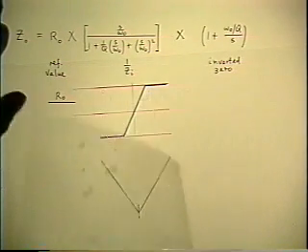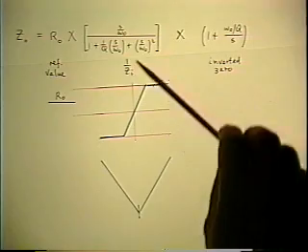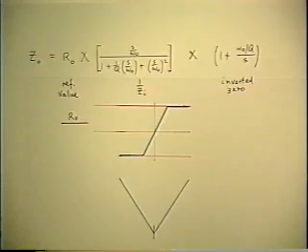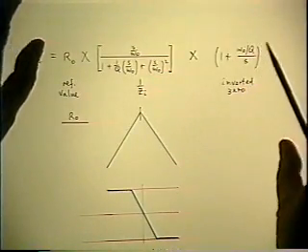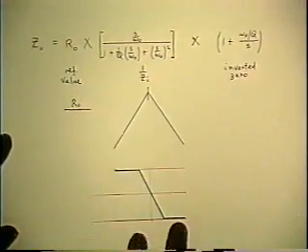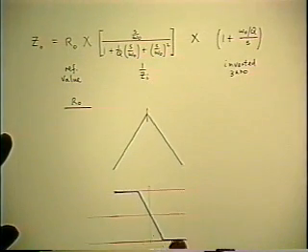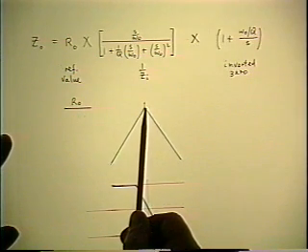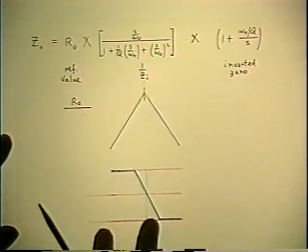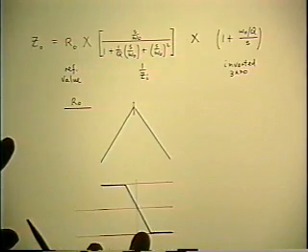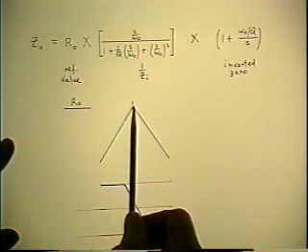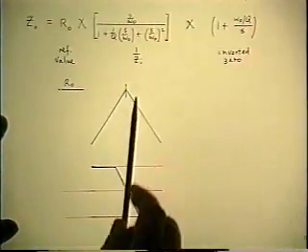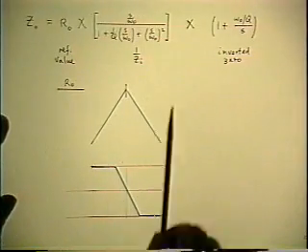So I take away the overlay, take the numbers off it, and I have to find its reciprocal. So I turn that upside down, and all that's left to do is to position this vertically and horizontally to fit with the R0. And again, the asymptote intersection we already know occurs at R0, so the proper vertical position is there, where the apex is at the R0 level. And the omega 0 is wherever I want to put it, in the horizontal direction.